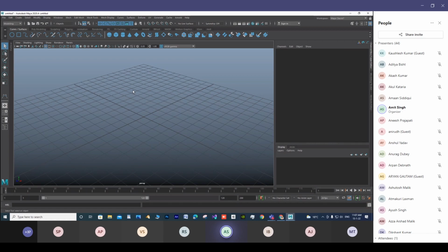In earlier versions of Maya, you can find three kinds of modeling directly visible on your screen: NURBS modeling, subdivision, and Polygon. Polygon is more in fashion, you can say. Even if you work in NURBS because something is created very easily, you have to convert it into Polygon. That is sometimes time-consuming, because once you convert, you have to correct your loops or mesh flow, since it sometimes creates high density in one portion of your model. It has to be uniform.